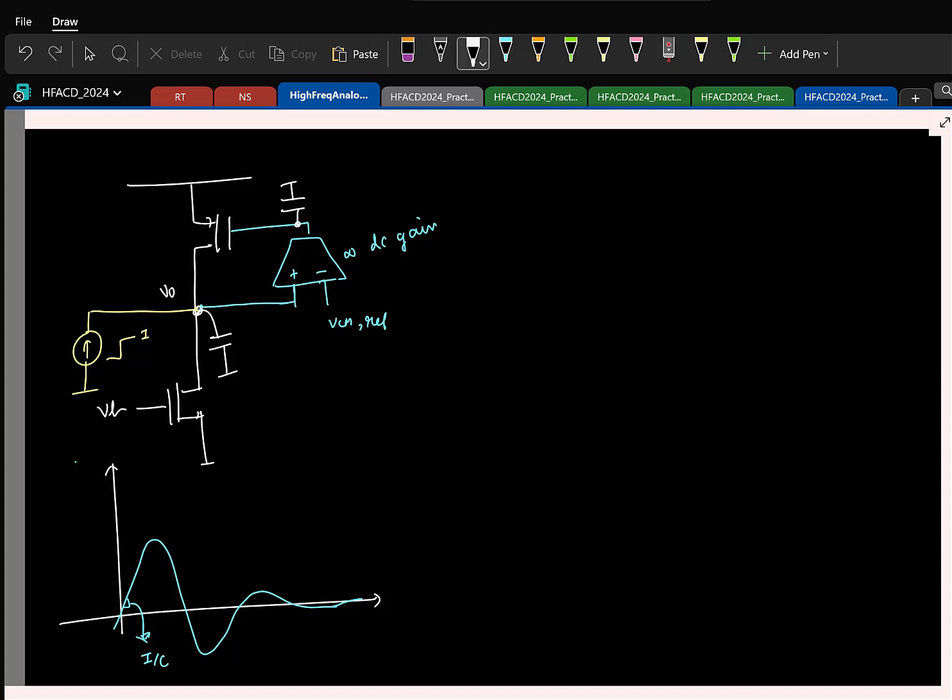See, the thing is, I have applied the step current, and I know that if I observe the voltage here, it has some kind of ringing like this. So what might be the simplest elements you can put here to emulate the same behavior? Second order system, yeah, okay. So what elements? If you have only RC, do you think that will happen? Yeah, definitely there should be LC because there is some sinusoidal ringing. So you will have an equivalent L and C.